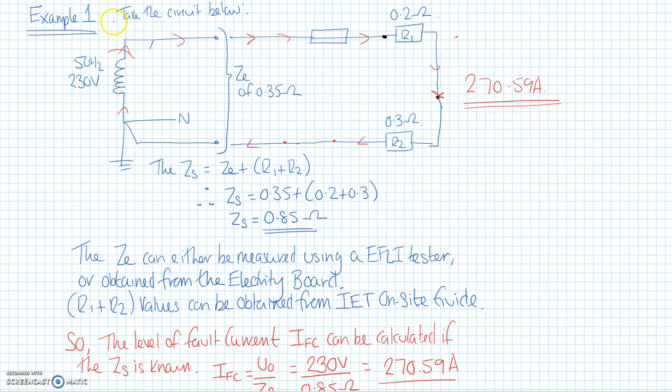So this is our secondary winding within our substation. This winding here is our secondary, 230 volts, and this would come through, out of the sub, and along the ground into our electricity board cutout. This would be in the premises.